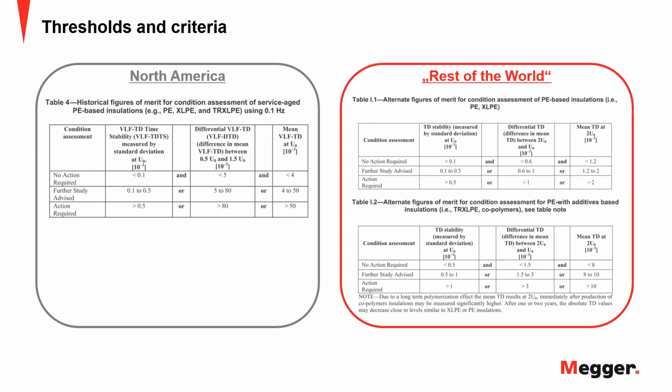So you can see, any paper cable that you test in the field, even a new one, a good one, has maybe a few hundred picocoulomb PD, and that's fine. It will live with us forever. But on the other side, the solid dielectric cable, if it has probably more than 20 PC, if you can measure it, then it would probably fail already. So it's the numbers. You need to know exactly what you're comparing these numbers on.